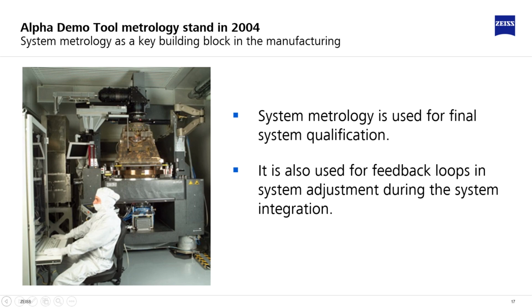A key point is the selection of the operating wavelength of the system metrology. The simulation of the ADT projection optics and the alignment processes predicted that a metrology at the EUV wavelength was not necessary. The expected differences to the established metrology at 248 nanometers were correctable within the scanner. The Alpha Demo Tool metrology stand includes interferometer and aerial image metrology, both at 248 nanometer wavelength.